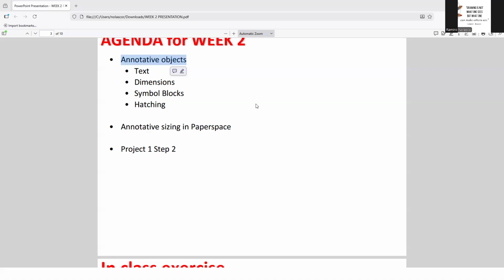You do not change the height of the text simply because you're changing the scale on paper. So you shouldn't do that in CAD as well. So your text, see at scale 1 to 10, if you simply zoom in and your text doesn't become smaller, it actually grows with it.